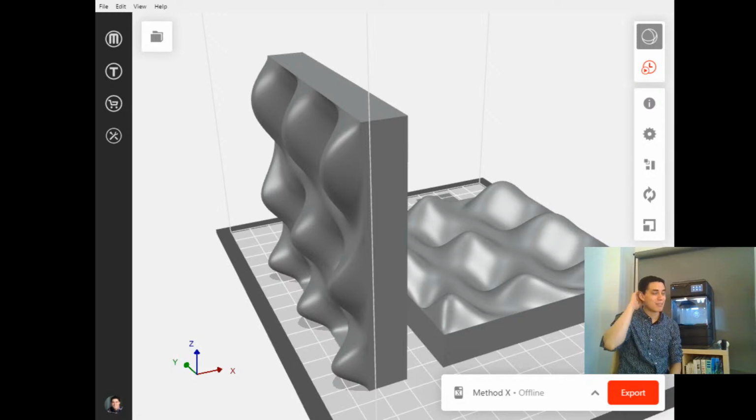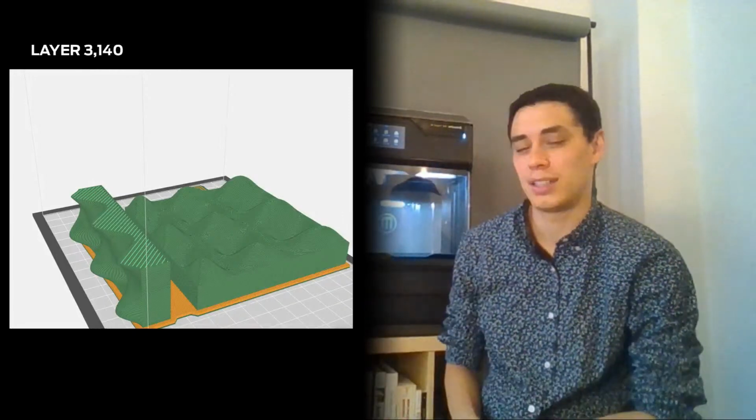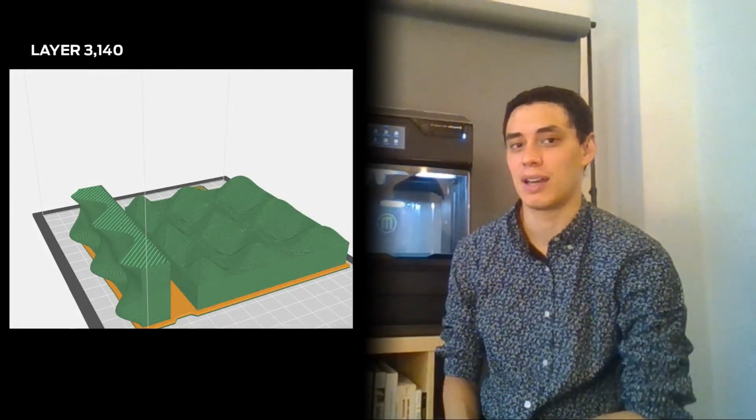However, that's always a trick question to answer, because as you hear people talking about, oh, we can actually do 50 microns, the Z height, the Z orientation of the part is never going to be as effective as the X and Y plane. Why? And the answer is right here. Let me bring that in. Depending on how you actually place those parts in the build plate, and this is what this diagram is trying to show, you're going to have quite a different type of slicing happening.